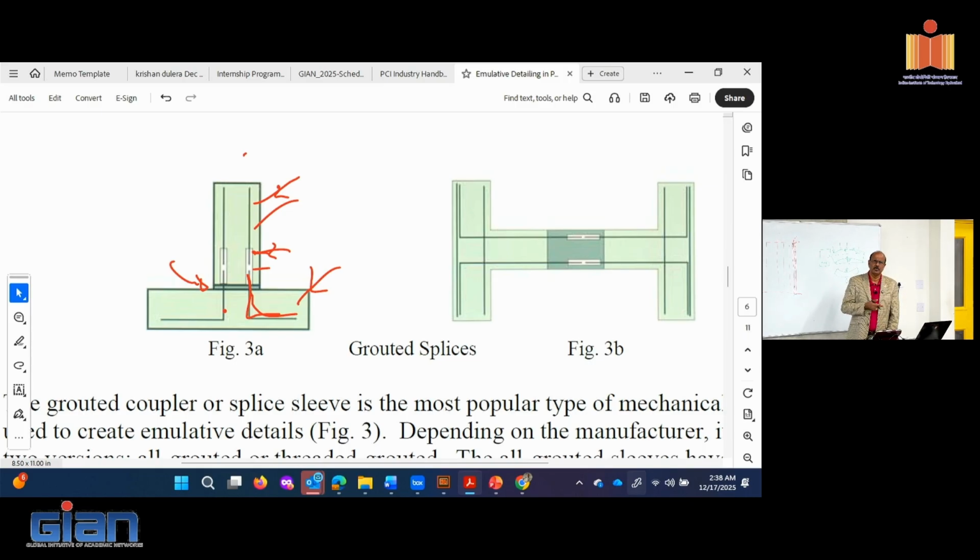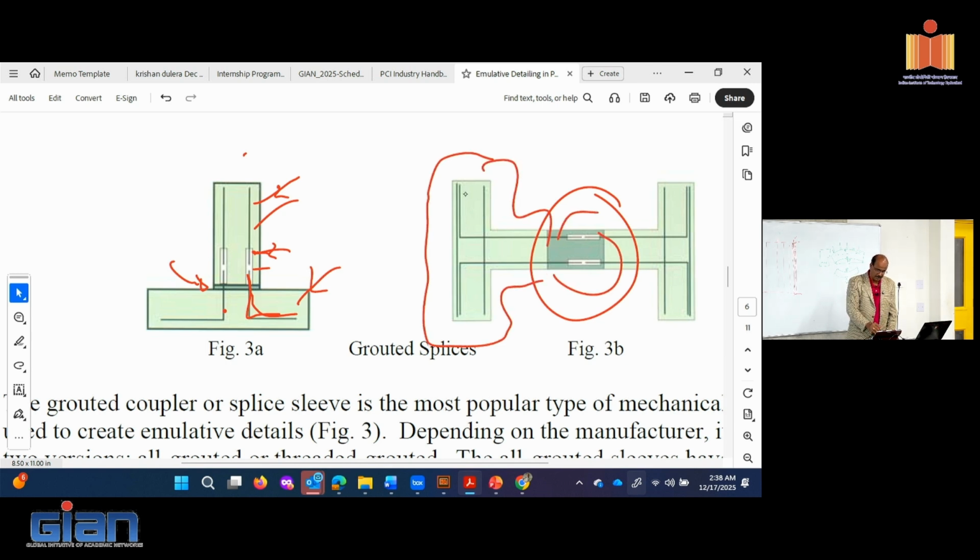There are different ways people have established grouted couplers, mechanically connected couplers. I think yours is mechanically connected couplers. Different things people have done. You could look at the same thing for establishing a frame where you bring in a T-section or T-shaped section, where this is connected horizontally. Vertically, you can use the same detail I've shown here. So you could see how these connections can be established.